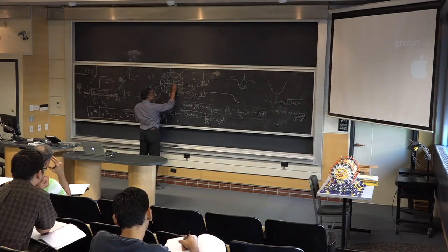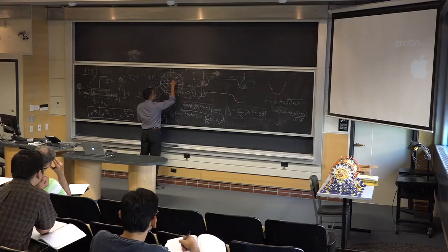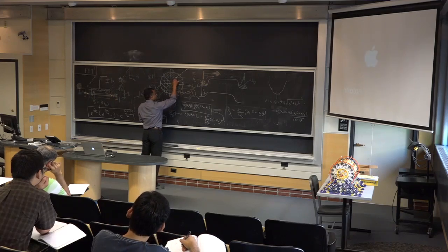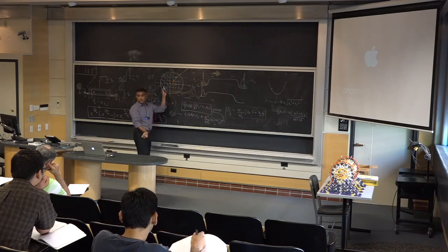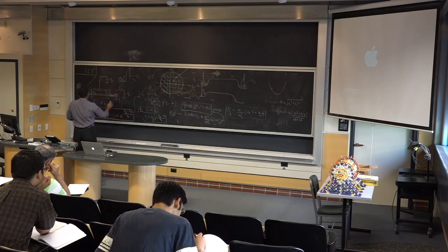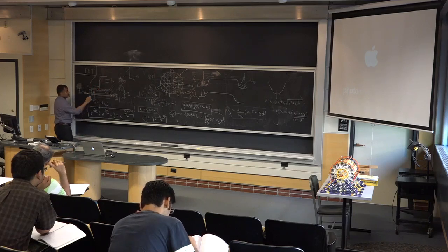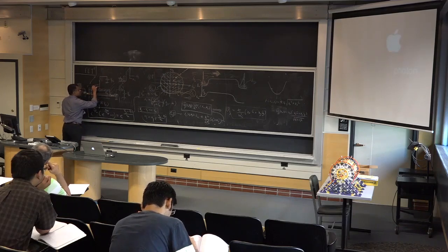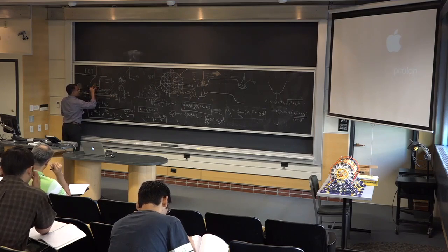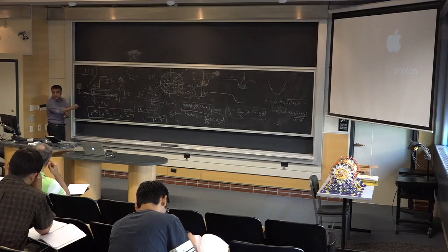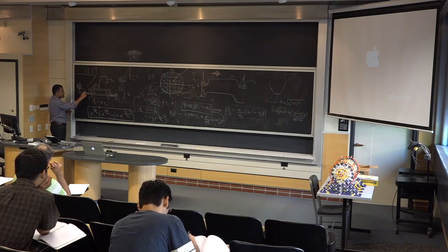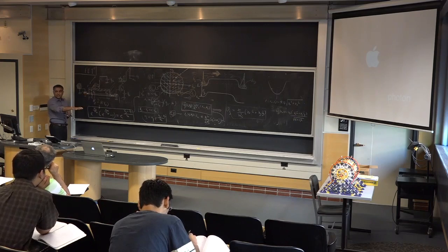Yes, this is moving to the right, but if you look at this one, it has a component of velocity to the right, but also a component going in the width of the device. Meaning, there are carriers not just injected moving to the right from the source, but carriers moving that way, that way, that way. You have this whole semicircle of carriers that get injected. Do you see that? Because it's two-dimensional in the metal and the contacts.